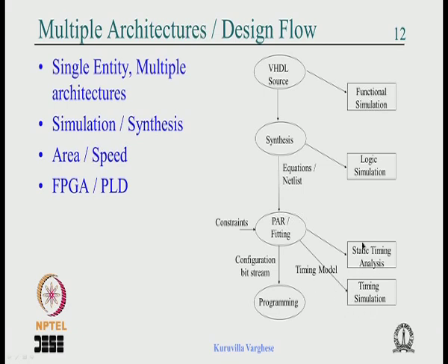So many times people at the beginning do something called static timing analysis. In all simulation you have the model of your circuit, you specify various inputs and you verify the output. That is the basic game. Suppose you have a clock and reset input, you give the clock, you reset it, you give various inputs and you check the sequence of outputs. That is how it is verified. In the case of timing simulation all the delays will be shown in the simulation.